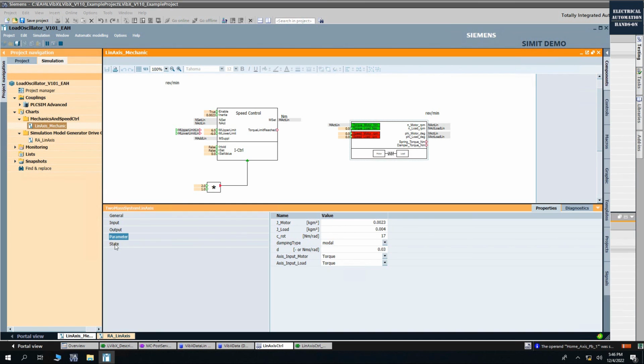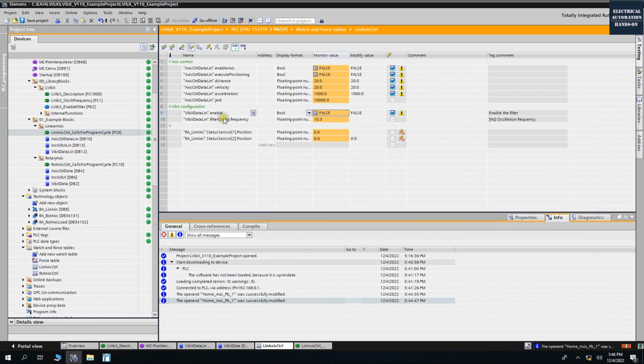And if we shift to the state, those values come from the calculation based on the parameters we set here. And the state's value shows my locked rotor frequency is 10.37. So that's why in the control, in this filter area, I set 10.3. Ideally, I should set 10.37.